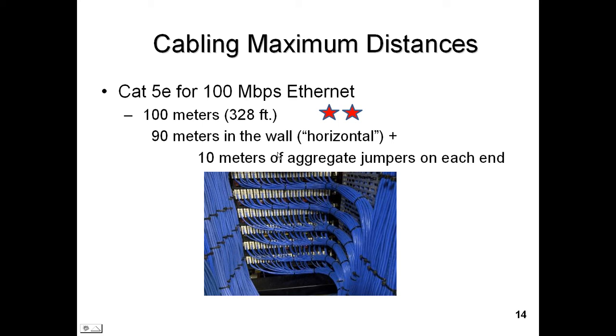But if you're using high quality cable and you're connecting it properly and you need to go an extra 20 or 30 feet, I certainly wouldn't be concerned about doing that, as long as you understand what you're doing and that you haven't sold it to the customer that we are installing this to the EIA-TIA standards, because that would be wrong, okay? And understand there are other ways to extend that distance.